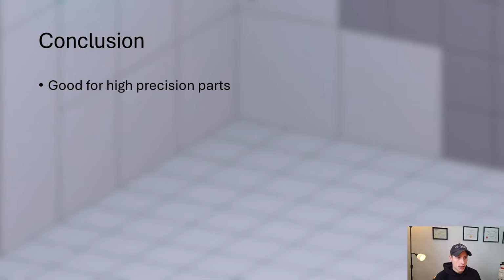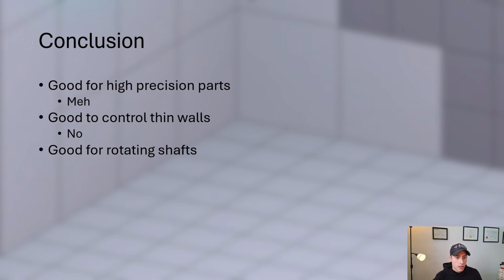So in conclusion, it's not better for high-precision parts because concentricity is not inherently a more precise geometric control. It's certainly not better to control thin walls with. And for rotating shafts under scrutiny, the argument kind of falls apart because we typically will balance shafts that need to be balanced.